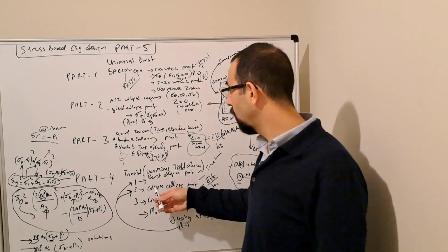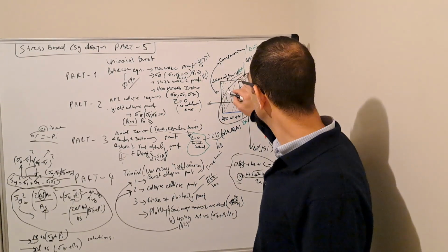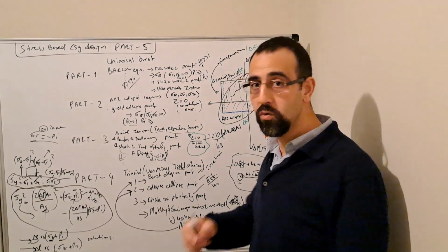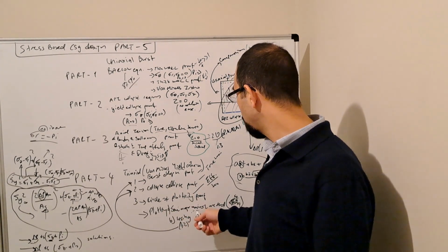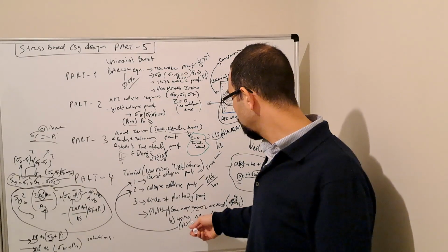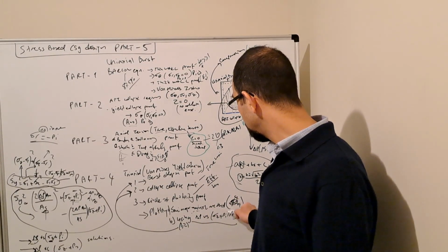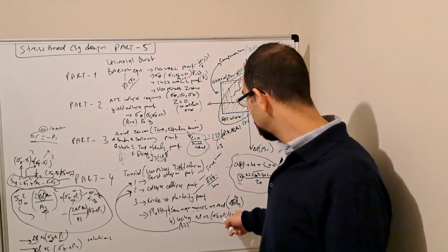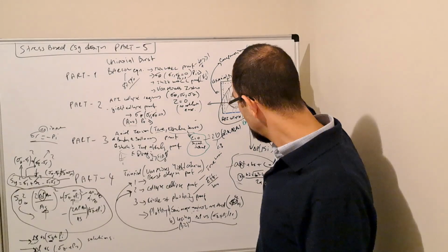And then on part number 4, we came up with this triaxial ellipse. So we have shown, as I mentioned, two methods. One is the semi-major and minor method, and the second one is using the delta P versus stress plus the backup pressure. It's either an internal pressure for the collapse side or the external pressure for the burst side.